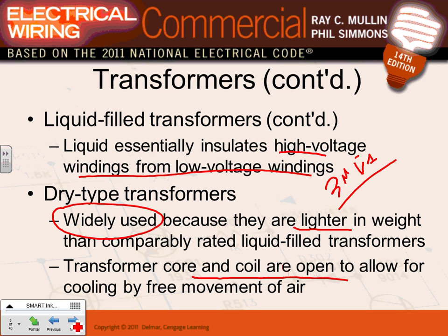So when you put your transformer in the building, Joe, you have to allow at least 2 to 3 feet behind the transformer. Can't remember, is it at least 2 feet behind and around the transformer, for natural circulation of air to cool it. You can't just put it in a room, close it from all sides, and give it 2 inches from each side. You have to allow natural circulation of air to cool the transformer. Cool? So who cares when you become a project manager? That's for you guys when you become project manager. You're going to place your transformer. Am I going to throw my transformer in a corner, locked behind it in a little cube here? No, you're going to allow 2 to 3 feet around that transformer, so it can cool.